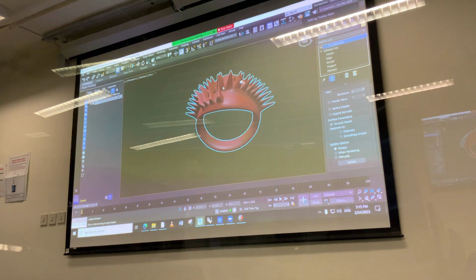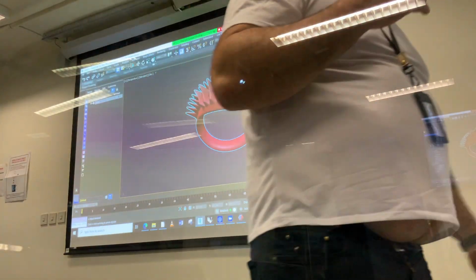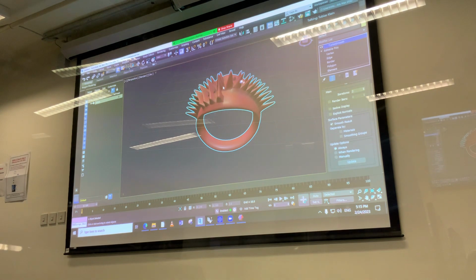The most crucial part, really, is super important. You bring over a low polygon mesh because the subdivision modeling, you can always make that as smooth as a baby's bubble. It's easy peasy to increase the faces, it's super hard to decrease it.